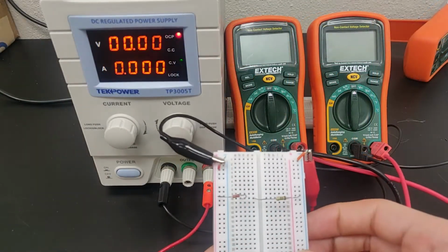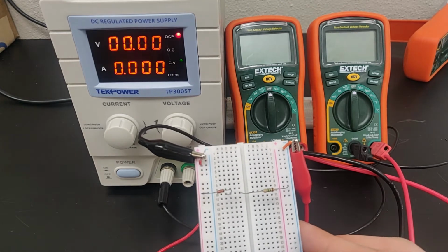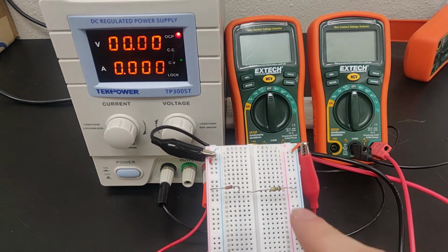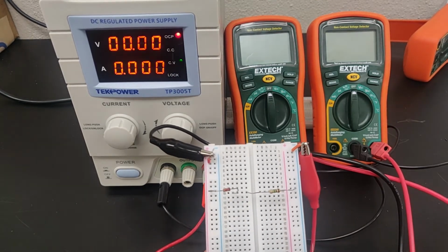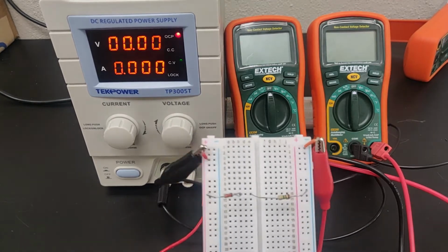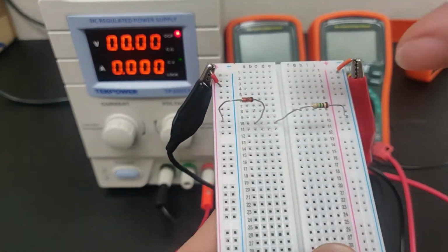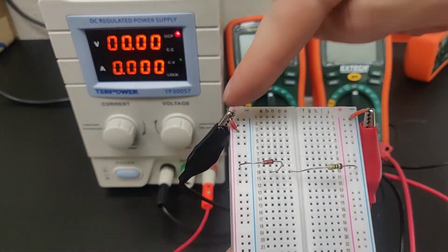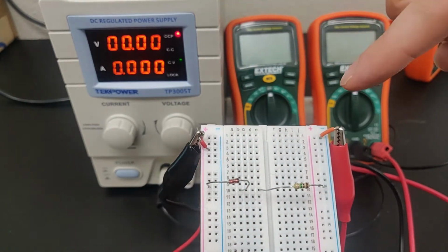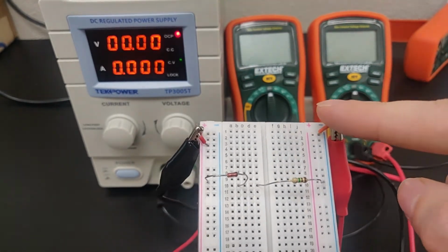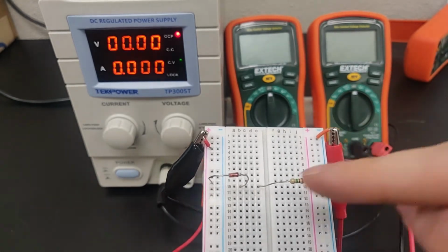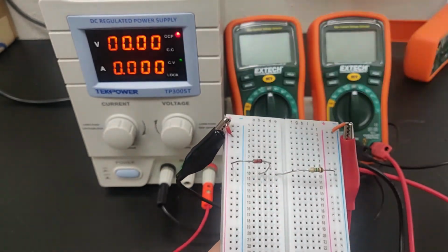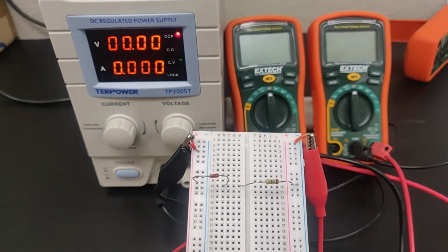Okay, so here is the circuit in our reversed bias orientation. I've switched out the 1000 ohm resistor with a 1 mega ohm resistor, which we'll measure shortly. And if you notice, I actually haven't changed the direction of the diode, still facing the same direction. What I have changed is the leads. So now that the red is on this right side, current's going to be coming in, going through this way, and now it's going to be going in that reversed bias direction. So I could have either done this or switched the orientation of the diode, doesn't matter.